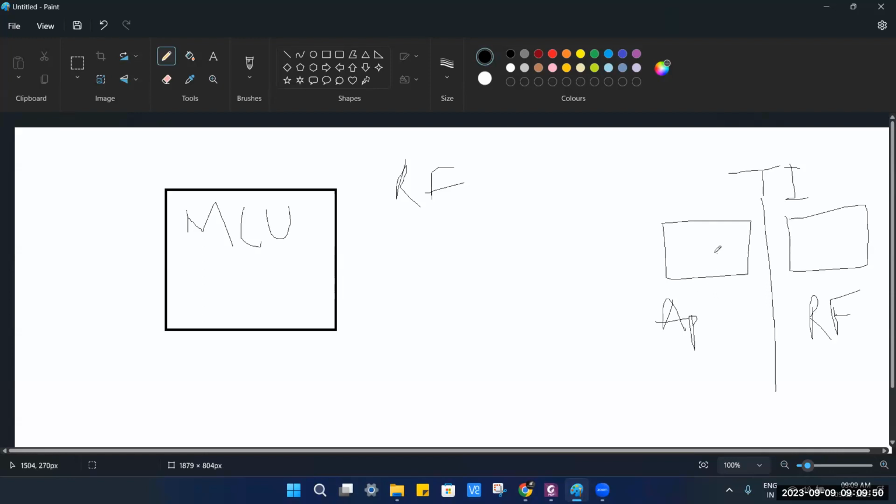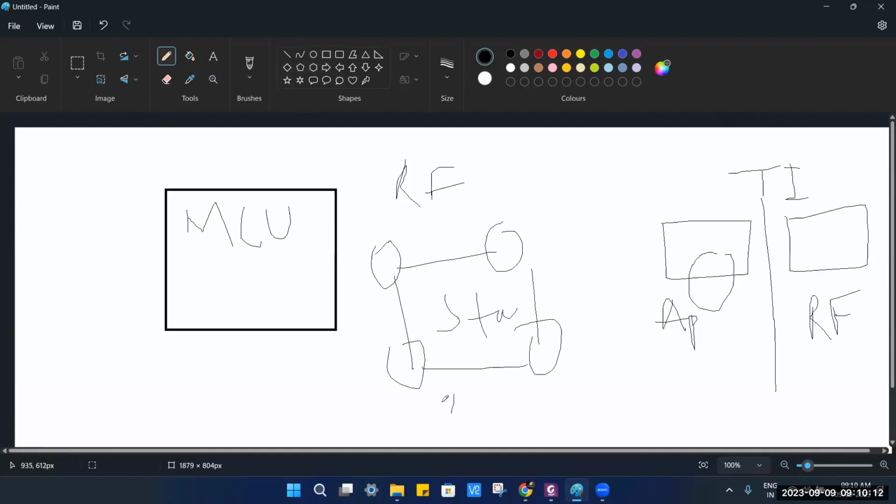Whatever data you want from the nodes, because in the smart meter architecture or these types of IoT architecture you might have hundreds of thousands of nodes, and they will be communicating with each other. Either they will use star topology or mesh topology. But right now, why are we not using star topology? Because there are so many limitations over there: in star topology you need some gateway through which you do the communication.